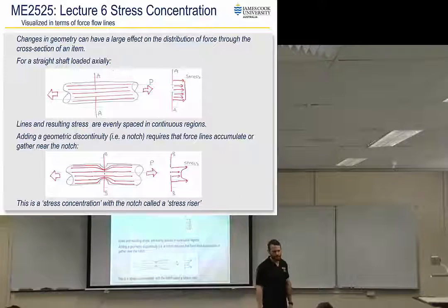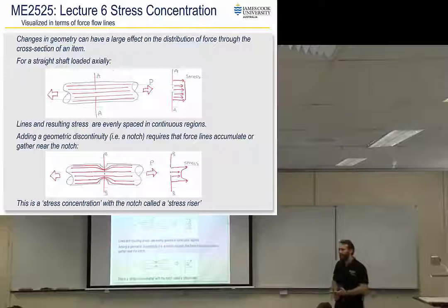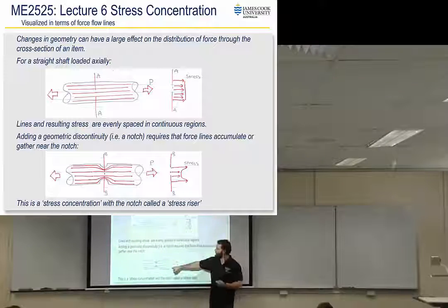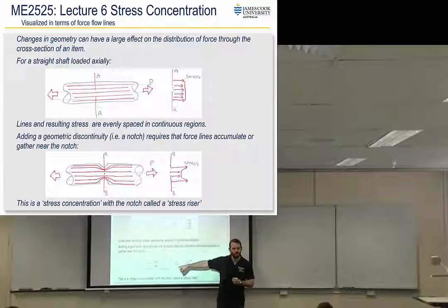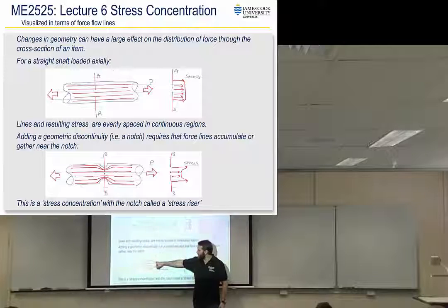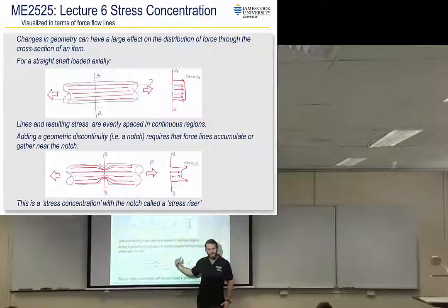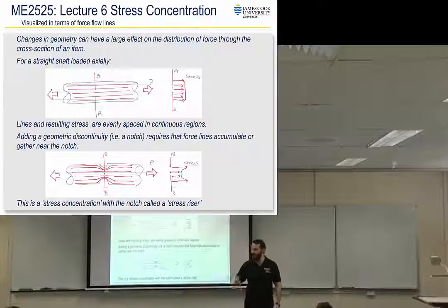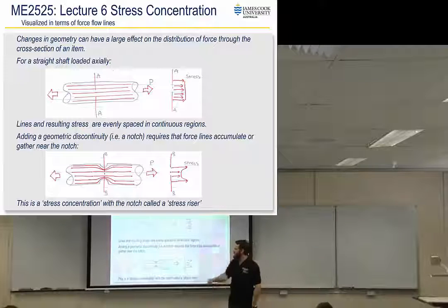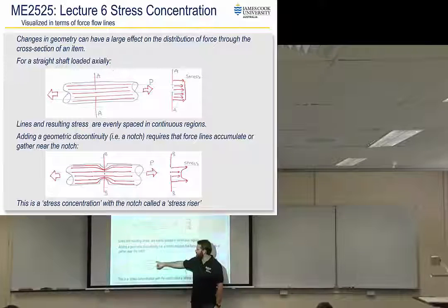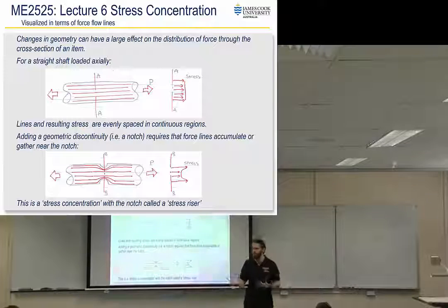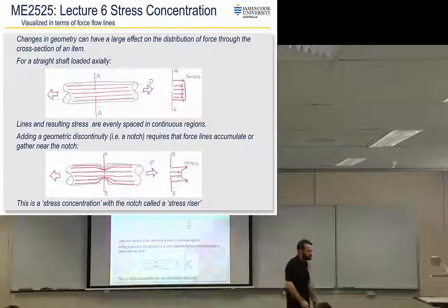Okay? So stress concentration will cause a large maximum, which is important because if you were to choose a stress element to draw your applied stresses for, firstly, you'd know that you want a stress element at the top there, and that it's an axial load, but through that cross section you don't have even distribution, so it's going to be different between the middle and the top and the bottom. So that tells you want one at either the top or the bottom. Secondly, if you just calculate P on A like we ordinarily do, you've not got the correct stress for that stress element. You need to do something else. You need to account for that extra stress that's coming from the stress concentration.